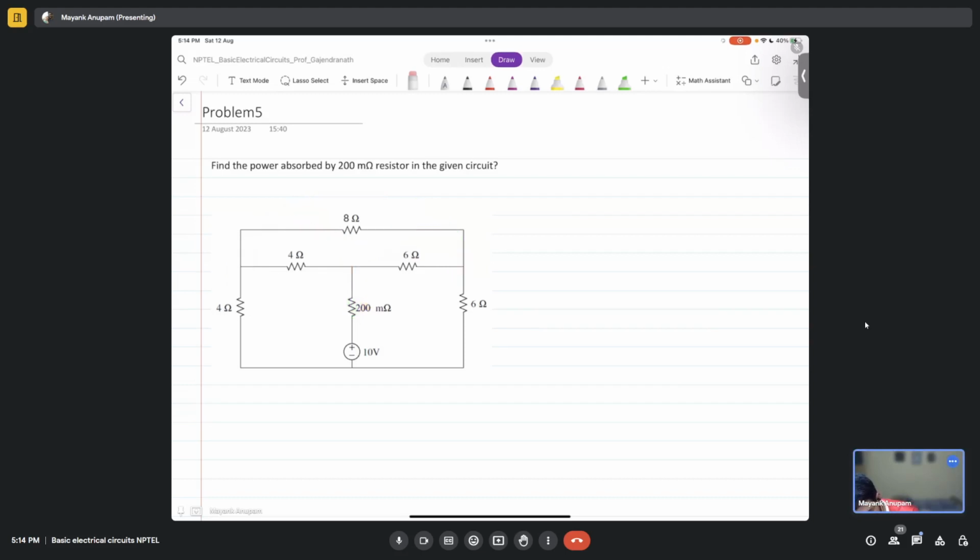So what is another approach? Another very simple approach is to use KCL and KVL, same age-old thing. In this case, what will be easier, KCL or KVL? Sir, KCL. Okay, so for KCL, you first take these three nodes. This node can be assumed to be ground. So this is V1, this is V2, and this is V3, right?